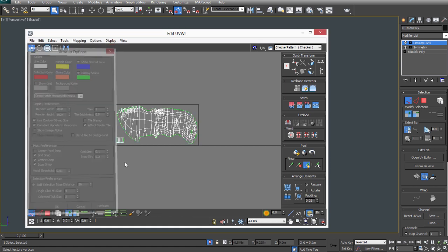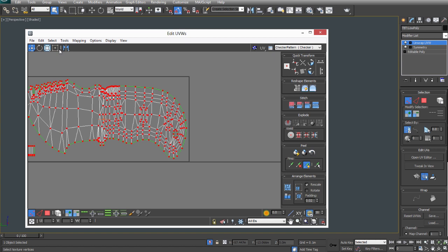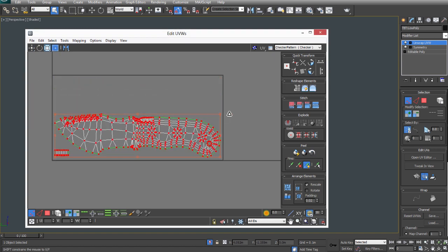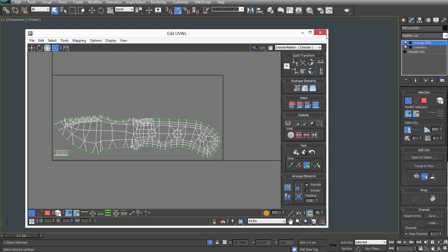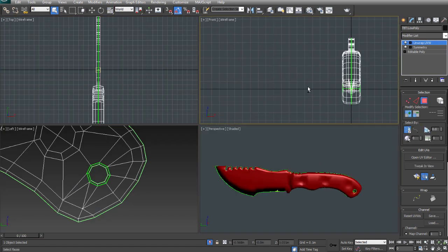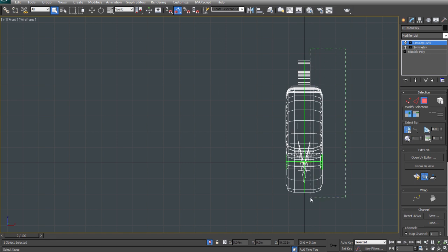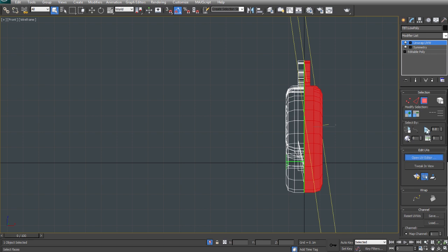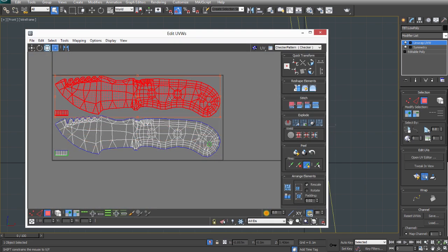So I'm changing the display preferences in the UV editor preferences window to 2048 by 1024 because I don't need a perfectly square texture for this. I want one that's slightly larger in width, because if I choose a square texture and only use half of it, well, that's going to be wasted space. And I don't want to stretch the texture to fill the square either.